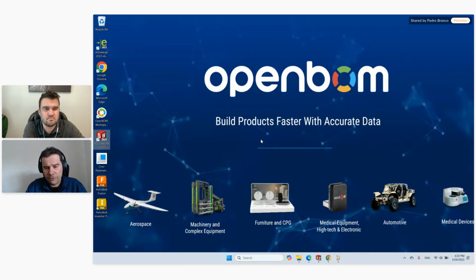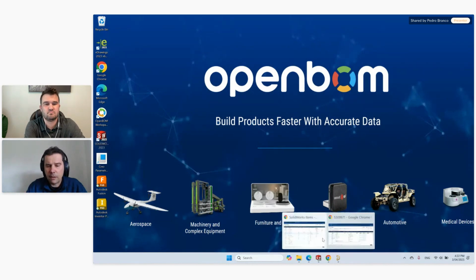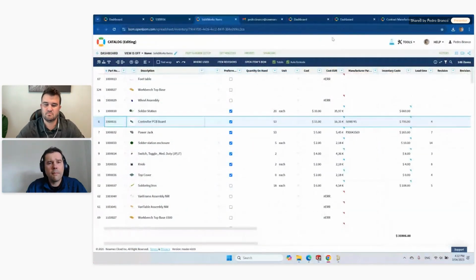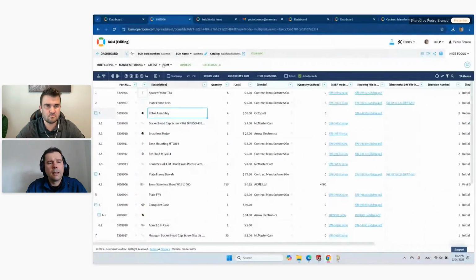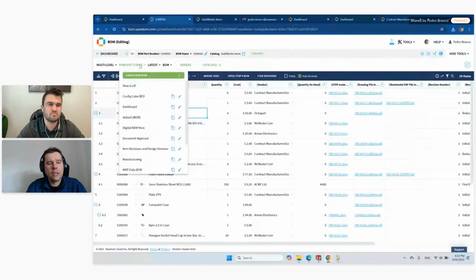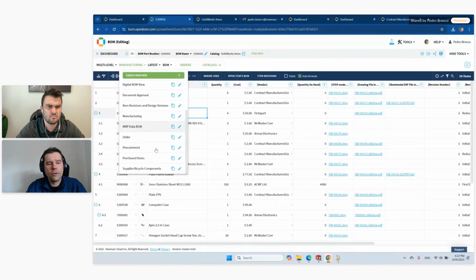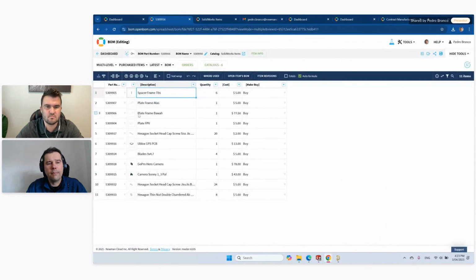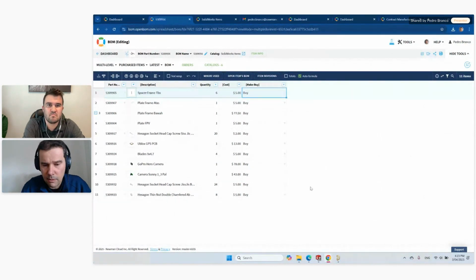And you can also use filters in your bill of material to group the information that you want. For example, if you look into a view, it can filter information. Let's move into a view that only shows buy items. So, for example, purchase items shows only items with the type buy. So you can use this sort of filtering to just show, let's say, manufacturing or CNC files. Just show me those rows and step files for CNC, and that's it.